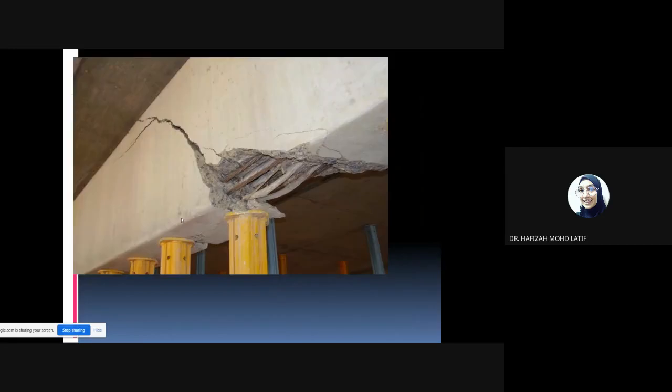So this is really, how do I say, horrible because you've got this, this is a cable, by the way. This is not a reinforcement bar, so they probably used the cable. So it cracks. When it cracks here, the load is supposed to be transferred horizontally. But when it reaches here, if you take the load reader, you will get a reading here of zero. The load will not transfer anymore. So it gets stuck. When it cannot transfer, it will go through wherever it can. So here it will become weak. When it is weak, it can break. When it breaks, the part above has no support and will also fall, collapse. When it collapses, the whole building has the possibility to collapse. Just because of this small one.